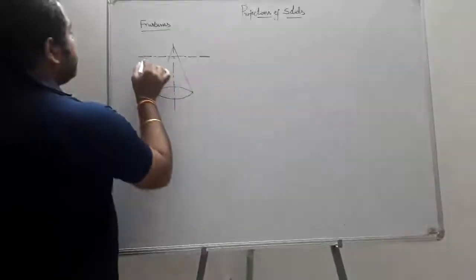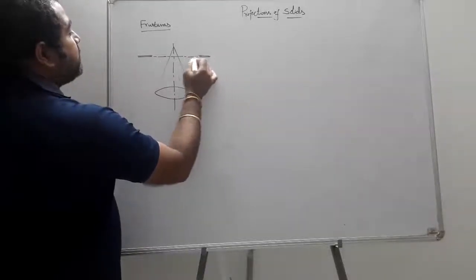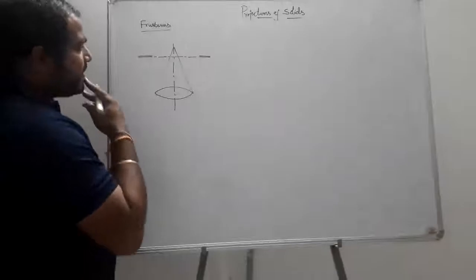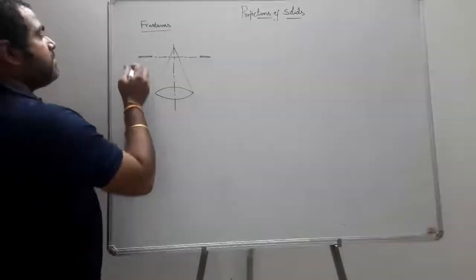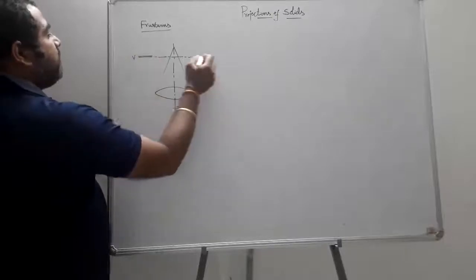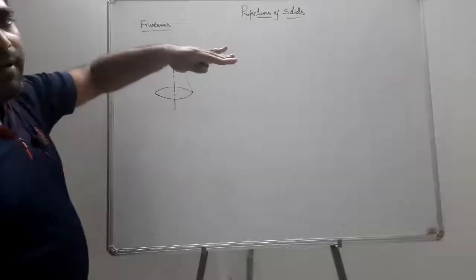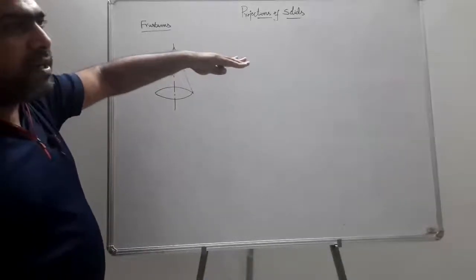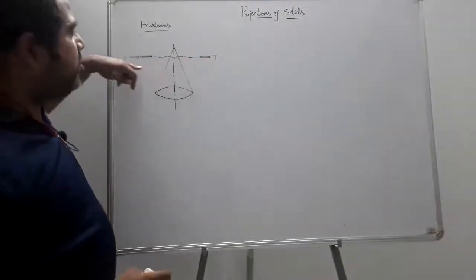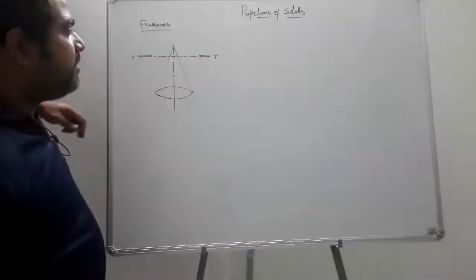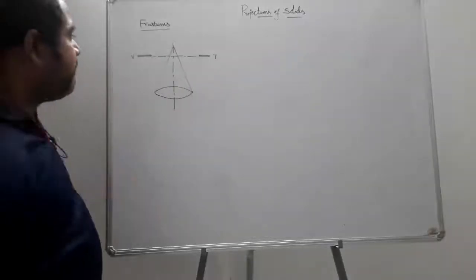Thick at the ends and thin at the center. If you take the cutting plane, this is called VT. Why? Because whenever you take a vertical cutting plane which is perpendicular to VP, and you see it as a straight line, then it is your trace VT, perpendicular to the vertical plane.